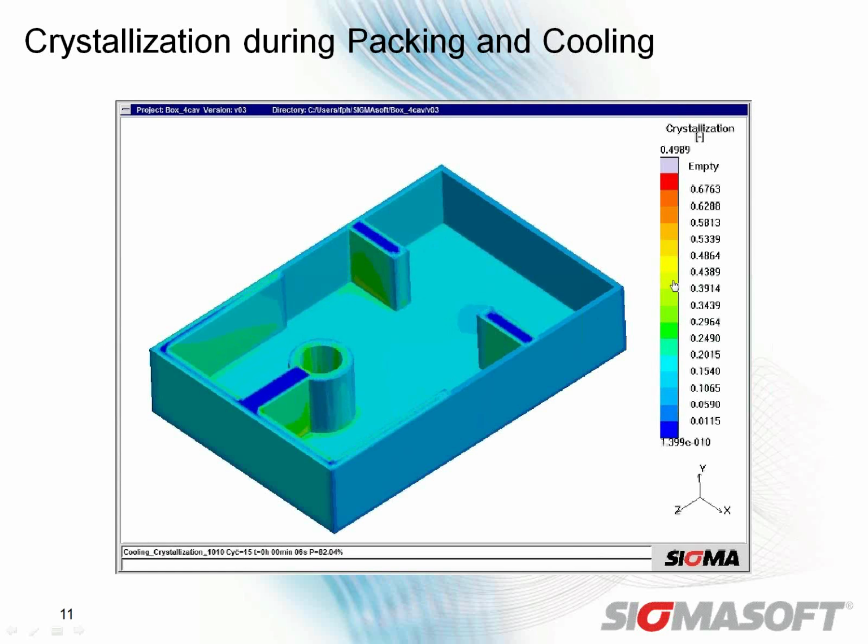I'm going to go ahead and stop this. So the more yellow, orange, red that it becomes, the more it's crystallizing. So we can see, we have like 67% crystallization here in the red, whereas the blue is where it started, 1%, 5%, so very low crystallization amount. And here, if I look at my time step, we're about 6 seconds into the packing. Actually, our packing time in this case is 7 seconds.